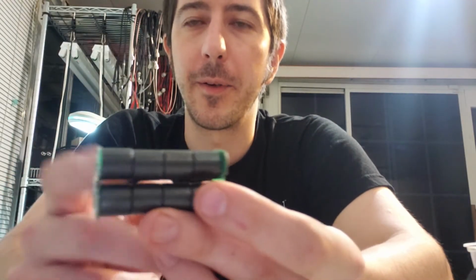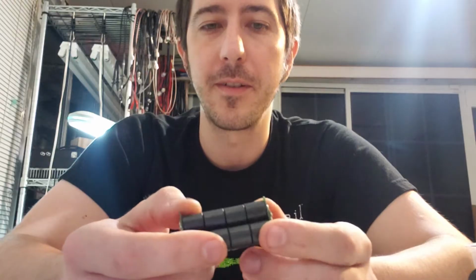Let's just say, for example, this has 1 turn of wire going through it. So we have 1 turn on one side and 1 turn on the other. If this was a perfect transformer, we could put 50 ohms into one side and get 50 ohm impedance on the other side. Or we could put 5 ohm impedance on one side, get 5 ohms on the other side. With a 1-to-1 transformer, you should have the same impedance on one side that you do on the other. But because of the imperfections, the leakage inductance, the magnetizing inductance, the core loss, the core saturation, all kinds of stuff like that, it's not going to be perfect. So you have to compensate it back to where you want it.